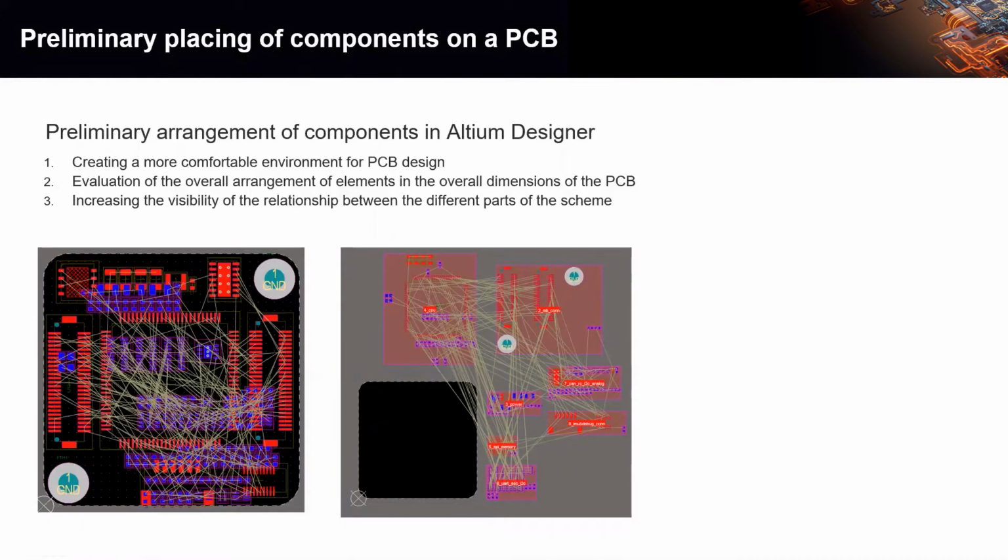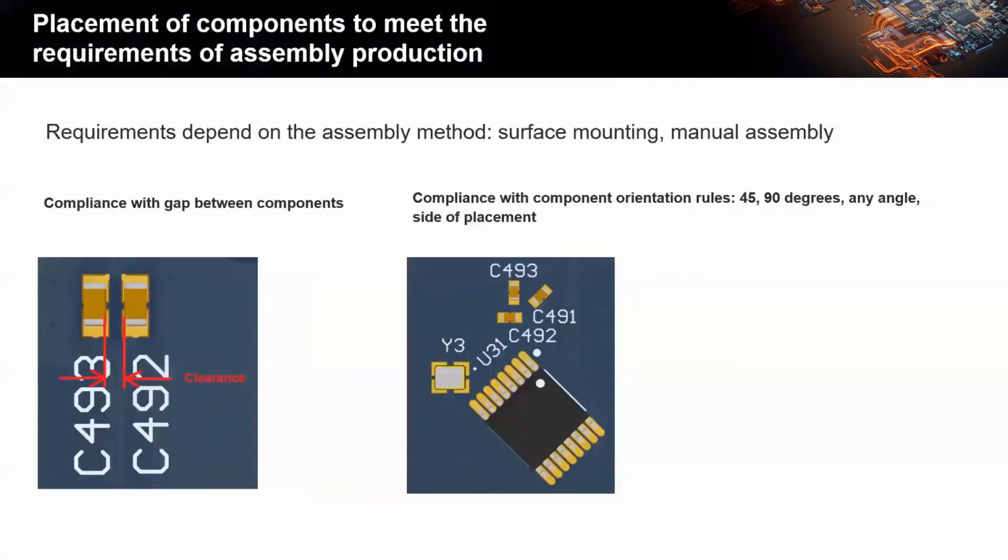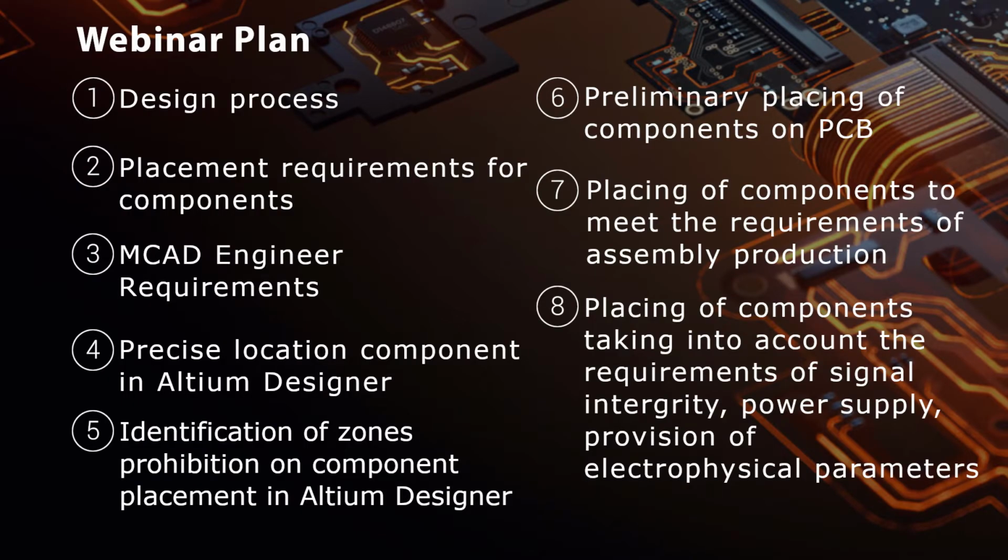And remember, component placement is very important because ultimately the routability of your PCB is going to be directly related to how well you place your footprints. And there's no substitute for experience here, folks. For the assembled board, there are going to be some notes and design rules that you create. For example, in my template PCB, I've got all my mechanical layers named with very specific names, like assembly notes, fabrication notes, dimensions, and we're going to take a look at that in a few minutes.